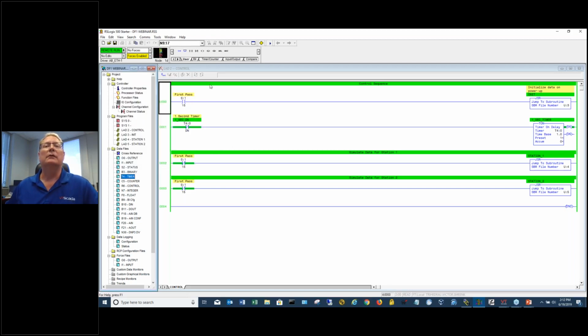I'm just going to jump in here real quick and point something out for anyone who came in slightly late. What we're looking at here is the software provided by the hardware manufacturer, and we're not actually looking at VTScada at all quite yet, right? That's correct, yes, we haven't gotten to that point yet. All of this is to configure the PLC, and then we'll have to match that configuration within VTScada so that they can talk correctly.